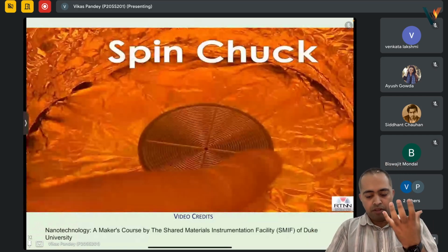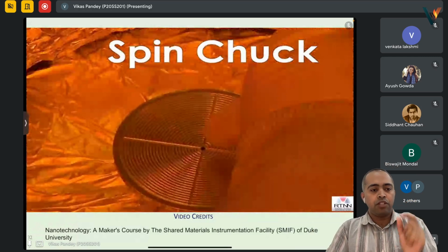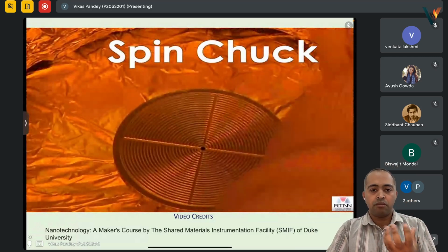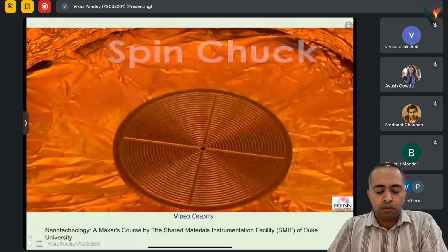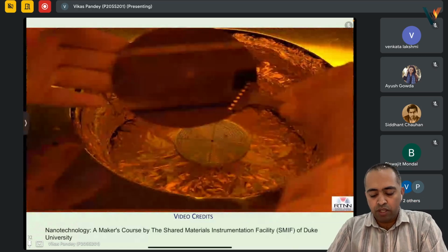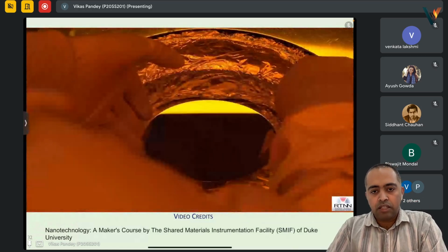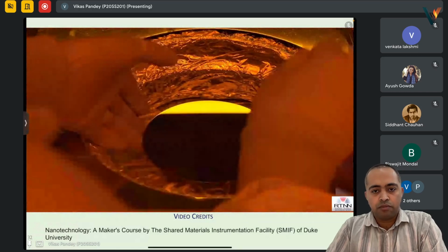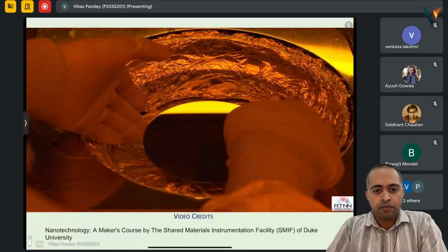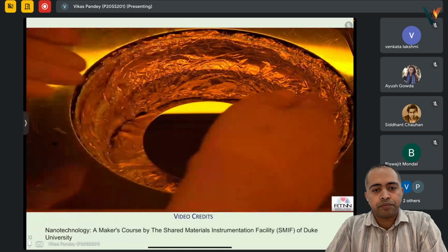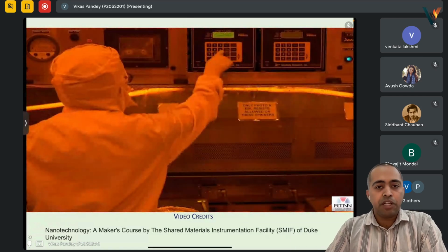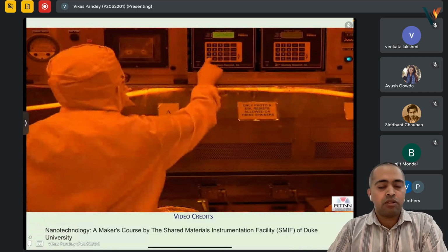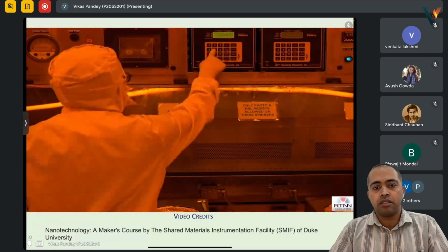It is a vacuum chuck which will hold this wafer using vacuum. So we put the wafer over it, and it will just hold it. Then photoresist is poured over it. The specific speed we want, like 4,000 or 3,000, will define the thickness of the resist coating.